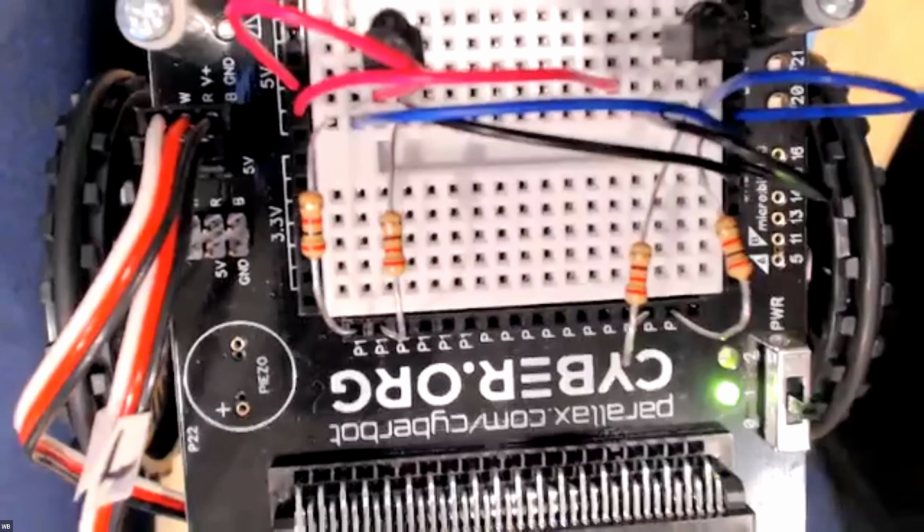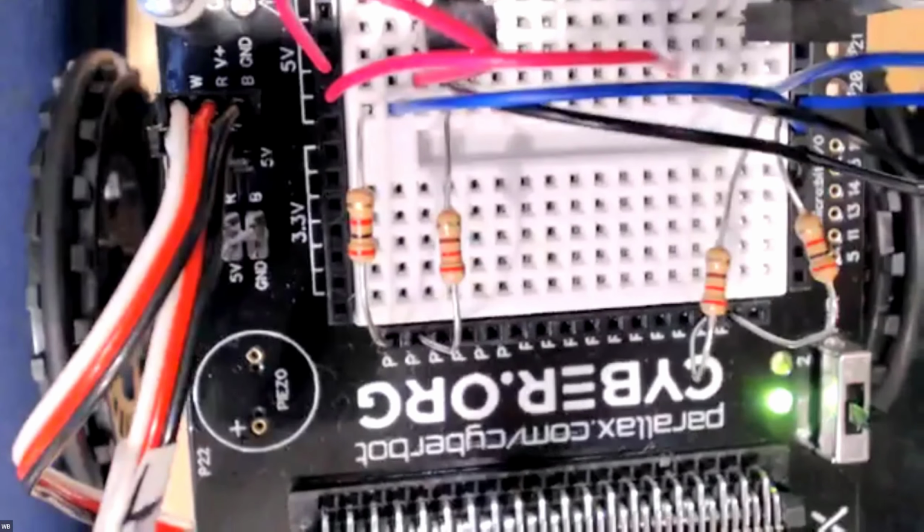Now let's start with your IR receiver. Is your IR receiver in the 3rd, 4th, and 5th rows? Bottom row is number 1. Yes. Okay, so your 2K, your red, black, red should be in the 2nd row. Your red, red, brown, I misspoke, should be in the 3rd row. Is it in the 3rd row? Yep, it's in the 3rd row. Okay, then the black wire that goes to ground should be in the 4th row. Yep.